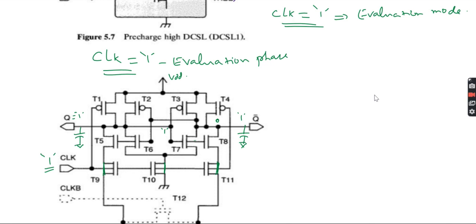If this transistor also is 1, then what will happen? You can see the position, this is 0, so this is driving the other inverter, driving that node, right? So this will be your 0. When it is 0, I will get a 1 over there, because when it is 0, this P transistor will be on, correct? I'll get a 1 over there.